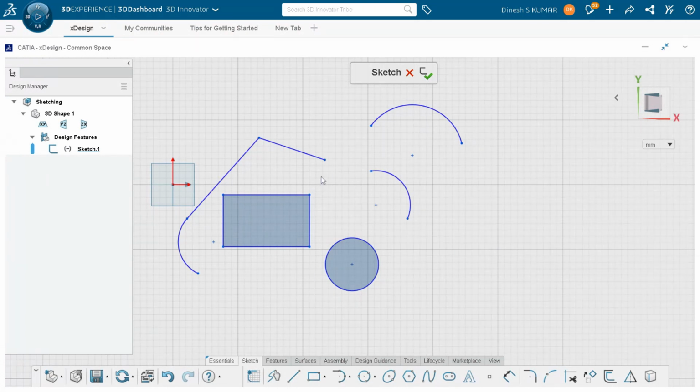Similarly, if you press and hold the left mouse button and drag left, this blue color box appears, and this blue color box will select everything which falls fully or partially inside it. So two different behaviors depending on whether you drag to the left or to the right, which is very powerful to do some complex selection quickly.